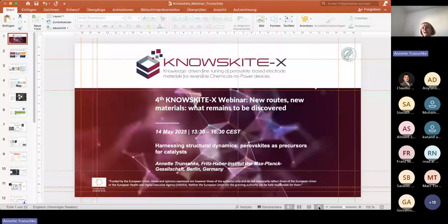weak adsorption sites which are good. If from the propane the propylene is formed, it can then desorb if it is located at such adsorption sites. But if it is located at these adsorption sites with a high heat of adsorption, a strong interaction, it may remain on the surface and be further oxidized to CO2. And our aim should be somehow to identify the nature of these sites and, by synthetic means, avoid the formation of these sites.